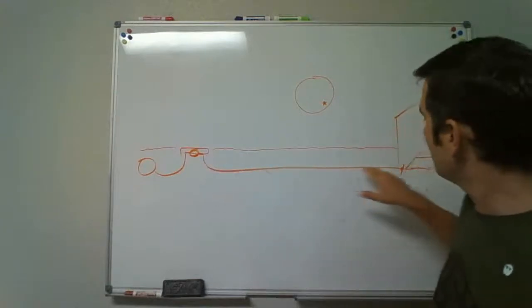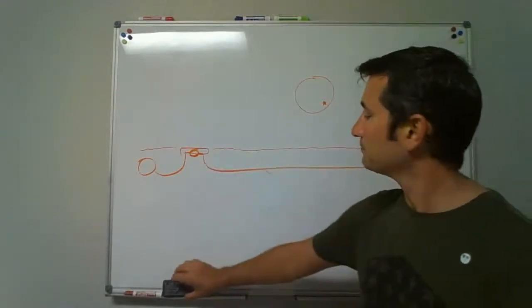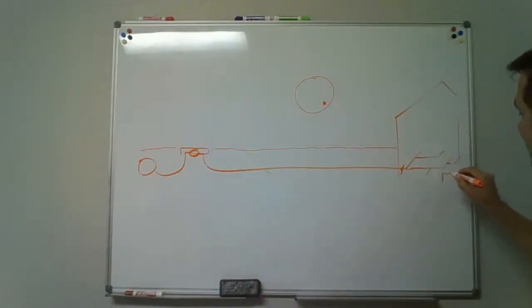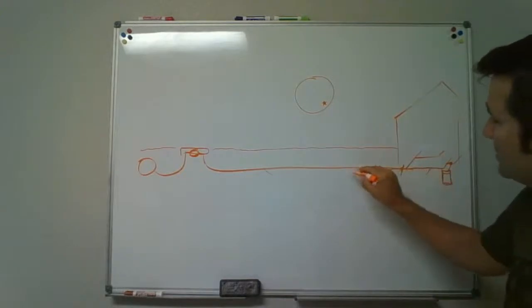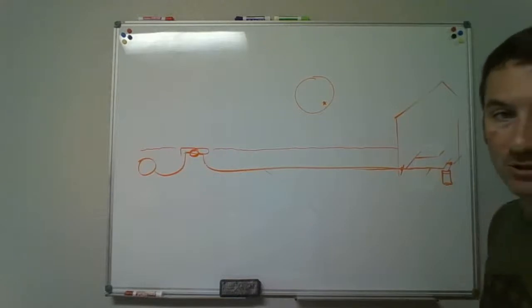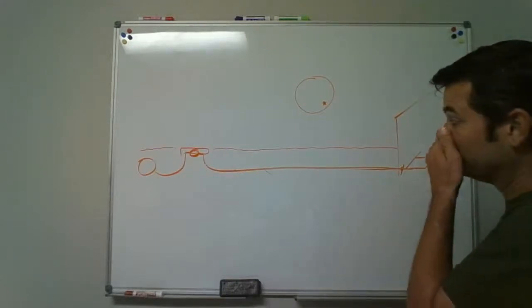This was all metal, copper piping, okay? Being all metal, this is all metal piping. Inside the house, he had his meter for his electrical panel here. And then I took a look at it, and it had a grounding wire coming off of this panel and attached itself to one of these copper wires, copper water lines, okay? What it was doing is using this metal piping that goes back out and into the ground. So it was using that copper water line as a ground for the electrical panel.